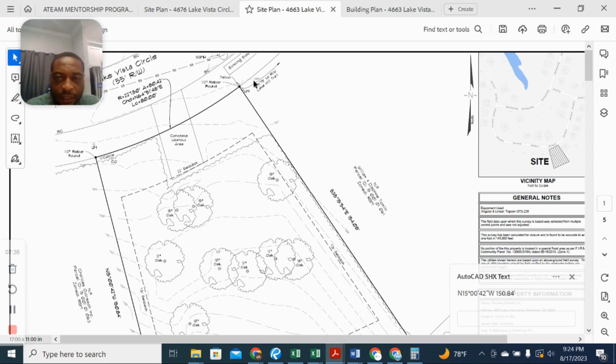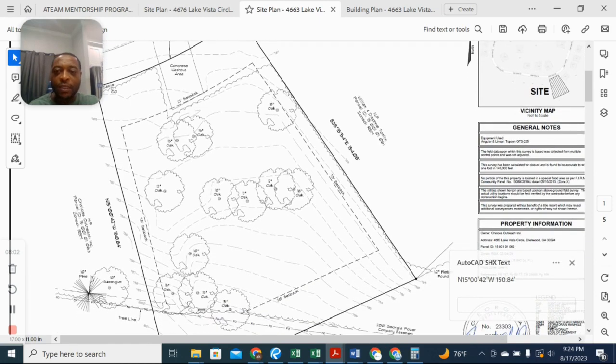Well, we're 786 here. As we move back towards the property, we have 787 here. We're going up a foot. As we move further down, we have 789. It's 3 feet. As we go, we are 790. You see what's happening here? Okay, it's going up. 791, 792, 793. So what does that mean? That means this property is gradually increasing towards the back. So we're sloping towards the back. It's a good thing because that means that our property now is draining down.